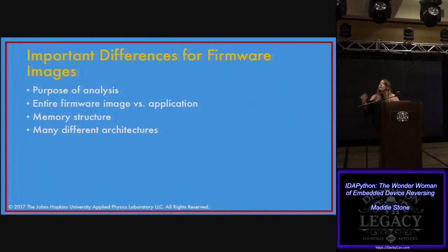And then you also have a lot of indirect memory accesses, because you might have a configuration table. The manufacturer, let's say, uses this same firmware image across all these different versions, maybe their legacy code too, and instead of updating the code, they just put a config table in there and say, hey, check this value. If it's set, you're going to use these features. If not, you're not. These are your jump tables, things like that. But if we can't see that interaction between the code and data, we're kind of screwed. How do we know what's going on? So we use scripts to help with that.